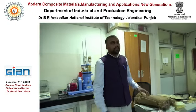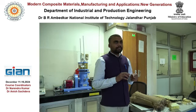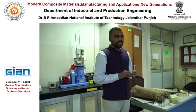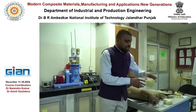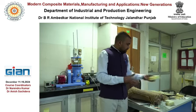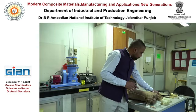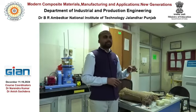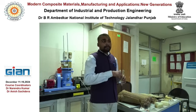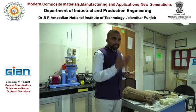For the composite material, we can have tensile testing, 3-point bending or 4-point bending tests, and compression tests. If you have sandwich composites, we can have a compression test, and for the sandwich we can also perform bending and impact tests. For laminated composites or 3D fabric reinforced composites, we can have impact tests, for example Charpy impact or Izod impact.